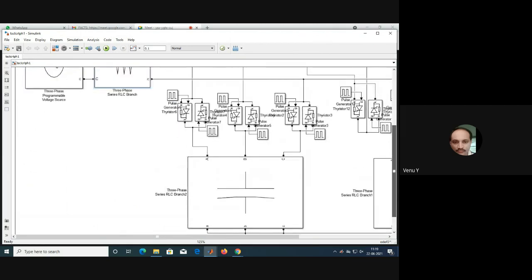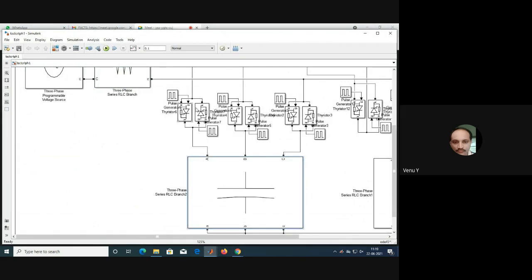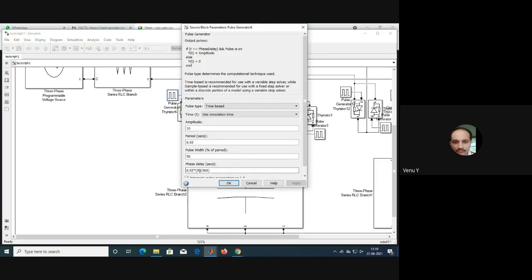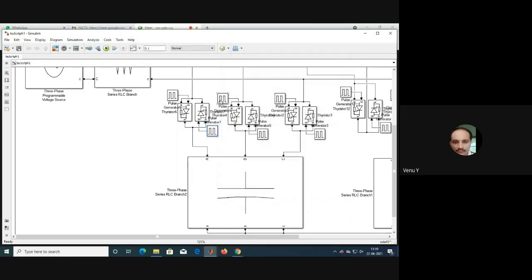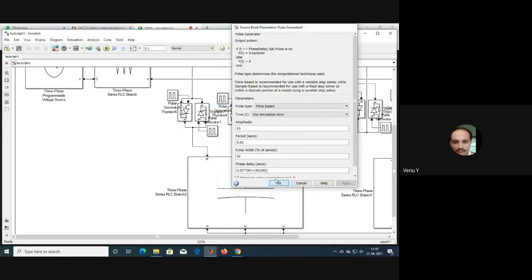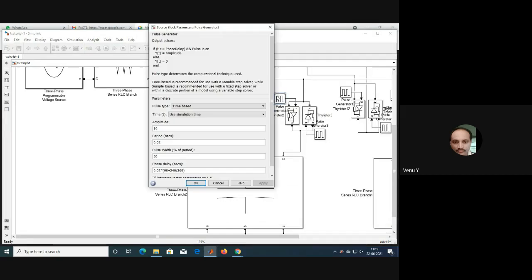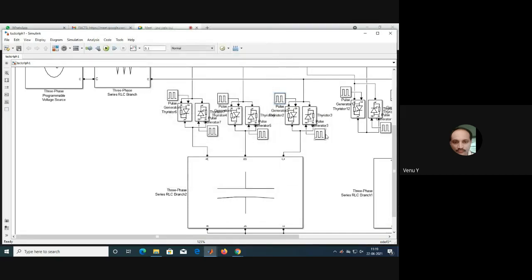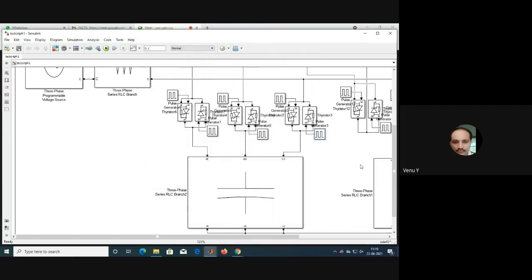So this is the TSC, 0.4 into 10 e power minus 4 capacitance, with first leg, second leg, third leg of TSC. Each leg will have 90 degrees, 90 plus 180, then 90 plus 120, 90 plus 120 plus 180, 90 plus 240, 90 plus 240 plus 180. This is the switching pattern of TSC.